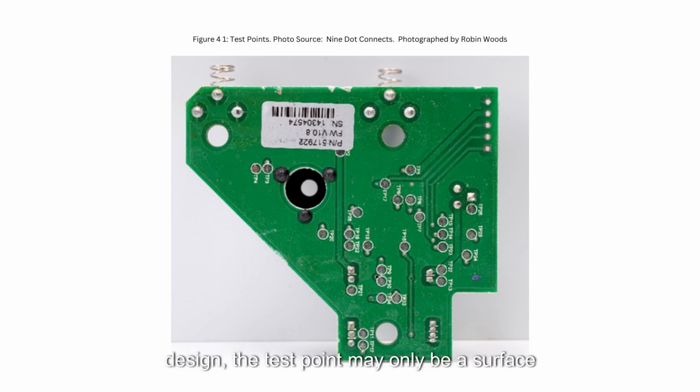In high-speed design, the test point may only be a surface mount pad, to avoid an antenna or a voltage reflection point in the signal path. If one desires to perform rapid testing, and the design is slated for high-volume production, test pads or test vias should be placed on a fixed grid.